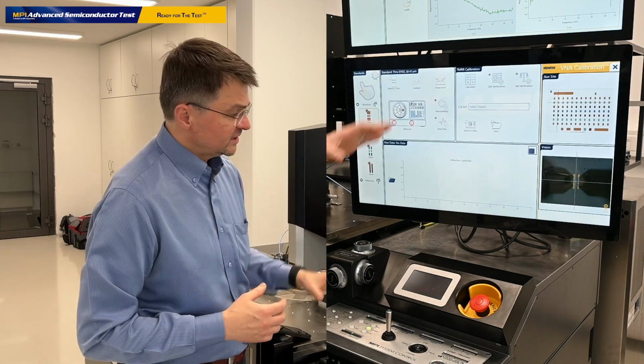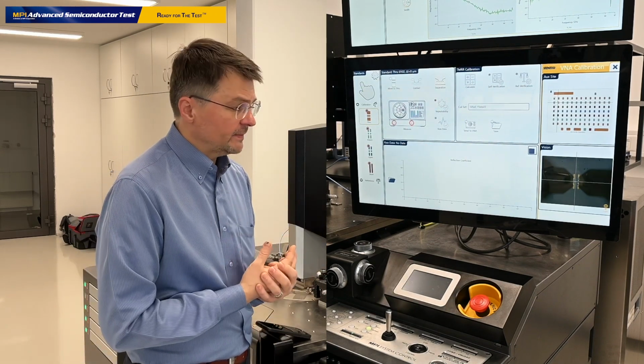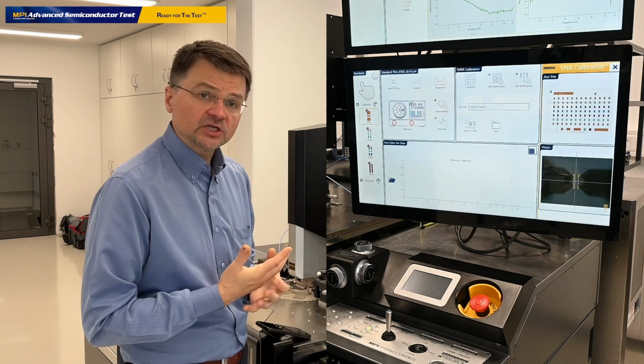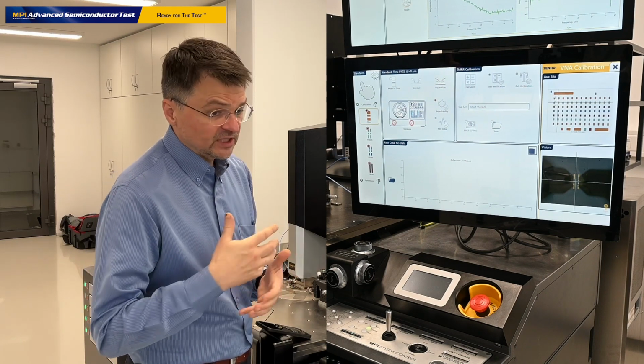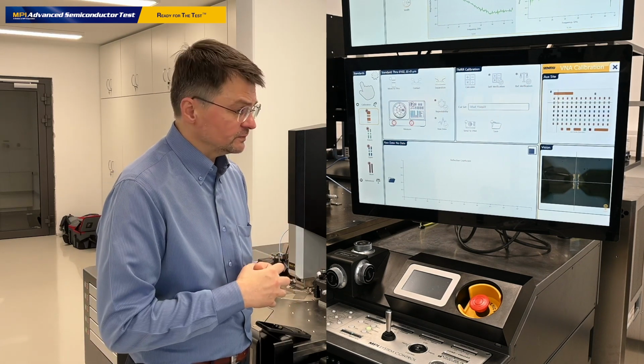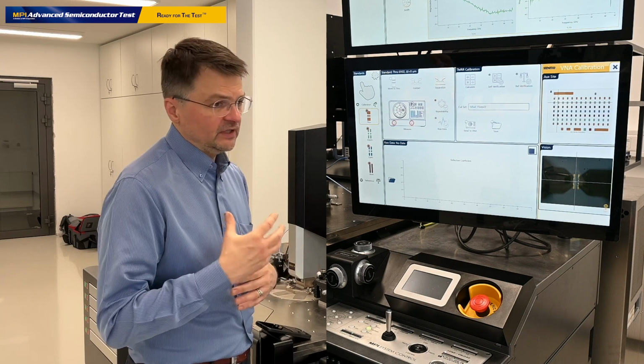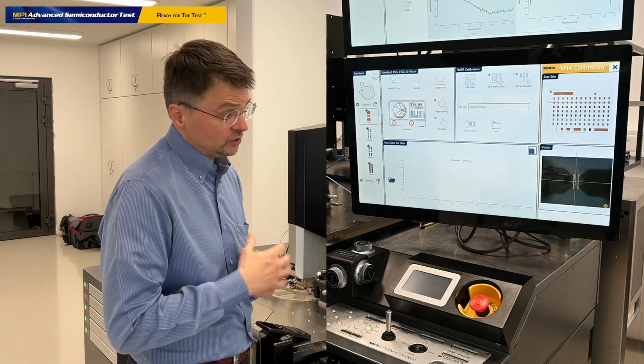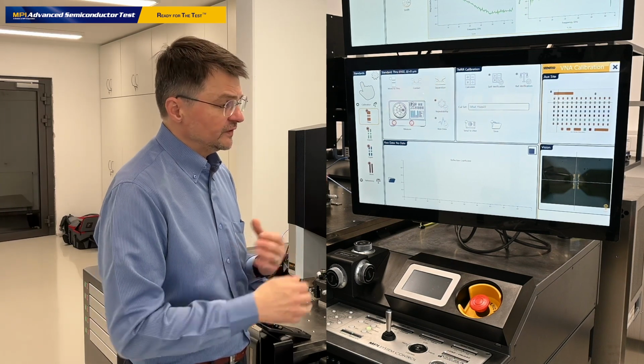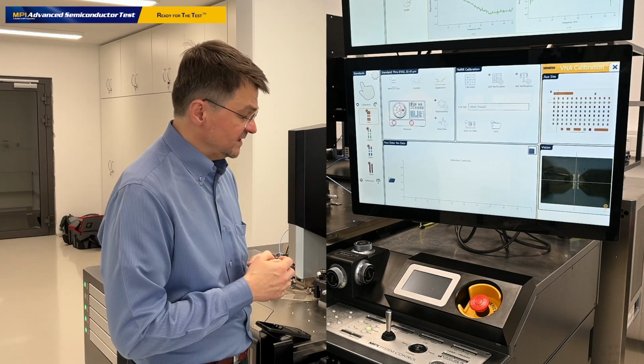So also TMRR has an additional capability for so-called self-verification. This is when we look into some additional data measured during the calibration process and make sure if the calibration was consistent and good enough and can be used for the further measurements of a device under test.